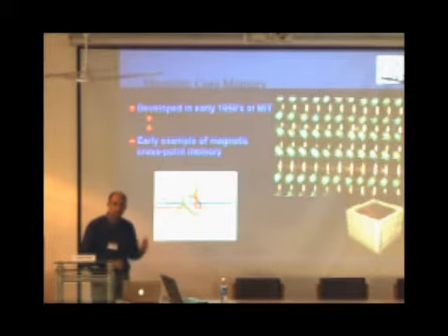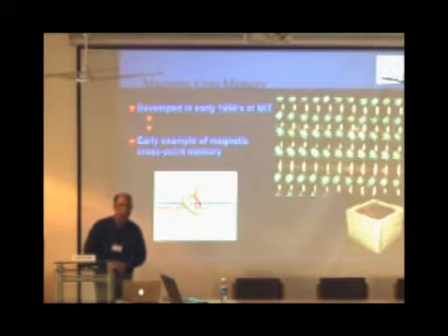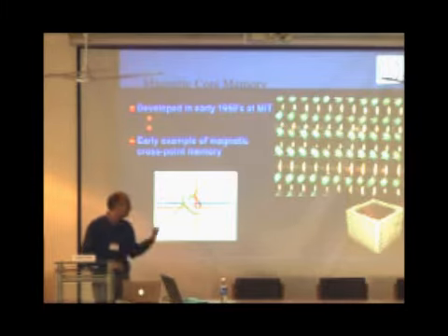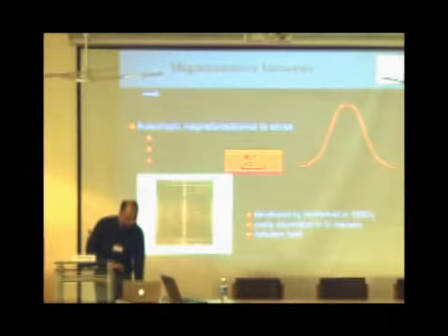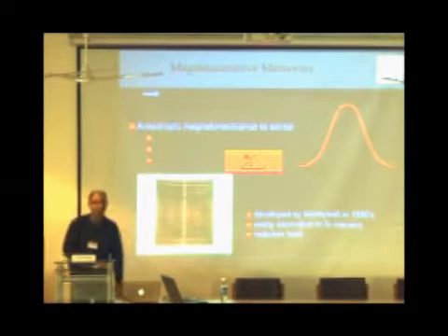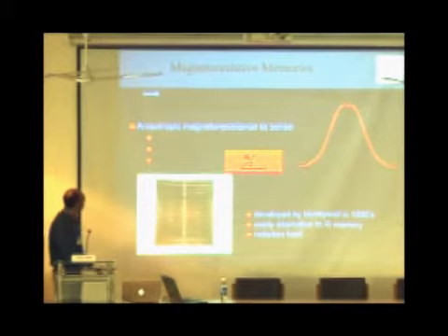The good thing about it is it actually works really very fast compared to SRAMs and DRAMs. It is limited not by the switching speed inherent in the magnetic bit, it is actually limited by the current drivers which could drive the fabric. So I'll come back to that point in the later part of my talk. So the same kind of MRAM was, sorry, the black isn't coming very well.